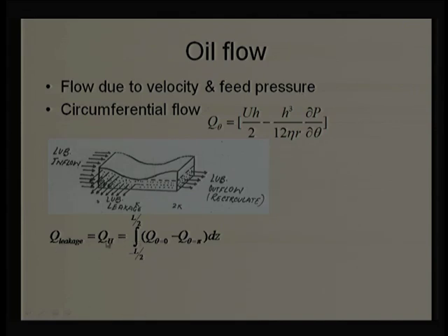We say QH can be calculated by integrating over the length, for two situations: the exit condition, that theta is equal to pi, and the entrance condition, that theta is equal to 0. That difference is going to give us the leakage from the bearing, QH coming out of the bearing, which gives us a cooling effect. In fact, it has been observed that 80 to 90% of the heat is carried away by the liquid lubricant leaking from the surface. So this gives us reliable results, reliable in the sense of 80 to 90%.